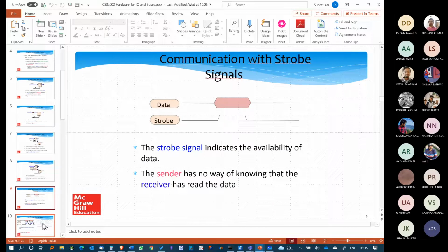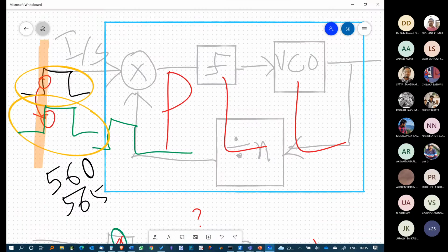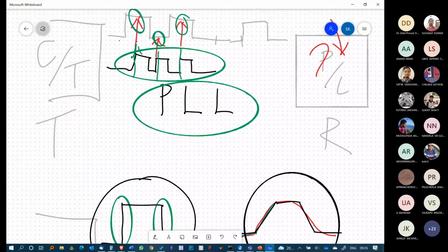All right. Then, instead of a clock, the fellow sending the data sends a strobe along with it. So these are all methods of synchronizing buses and I/O transfers. We are talking about this in context because whenever you do I/O, there is always an I/O from a CPU to a peripheral.